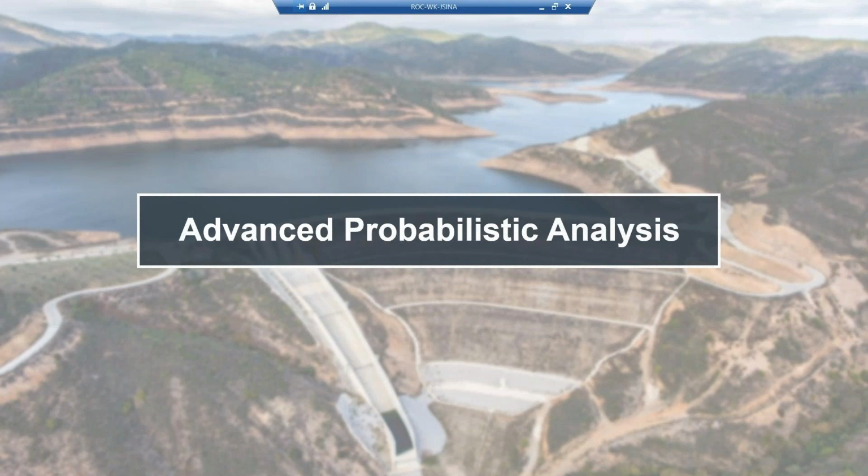The other question is, can you plot the statistics of the factor of safety curve? Yes, actually the way that probability of failure is calculated, first we create a distribution curve for the factor of safety, and then we find different parameters. This answers one of the other questions, that can we define probability of failure for the factor of safety of less than 1.5? Since we have a distribution for the factor of safety, you can choose a range, either factor of safety of less than 1 or between 1 and 1.5, using the histogram of factor of safety or CDF curve of the factor of safety.